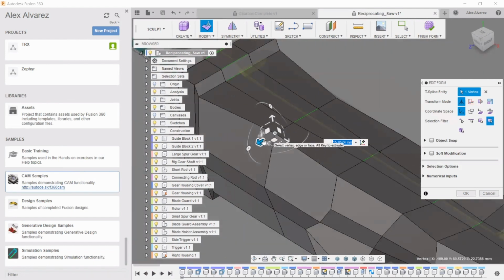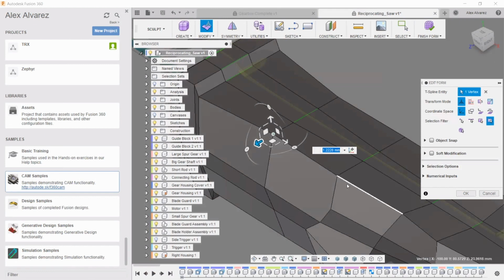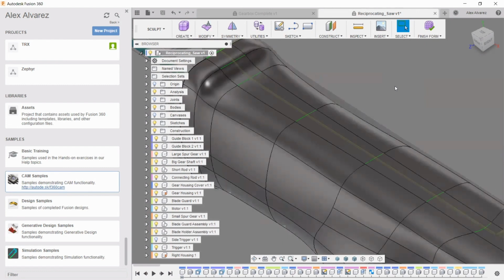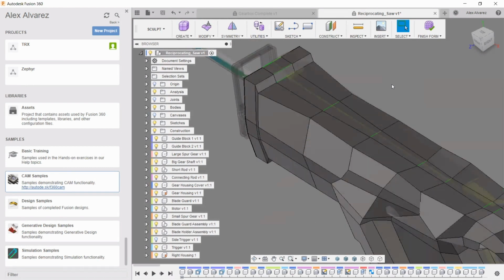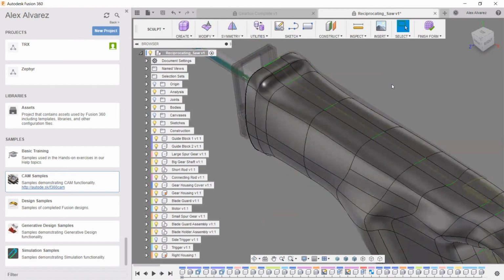and then drag this edge out. Right, so what you want to start doing here is start matching the edges. Make sure that they're fairly even, that they're maybe collinear depending on your design. So now if I exit out of this, Alt-3, notice that it looks much better here, right? So again, switching between box mode and your full-on T-spline view here.